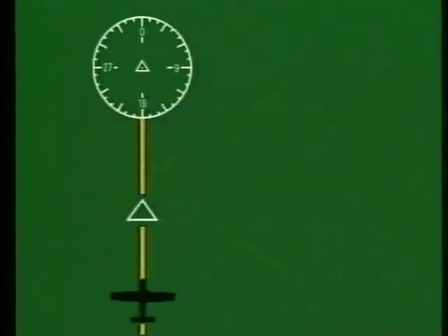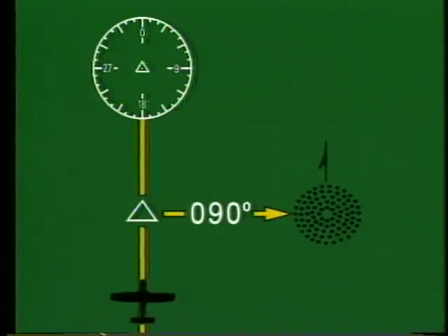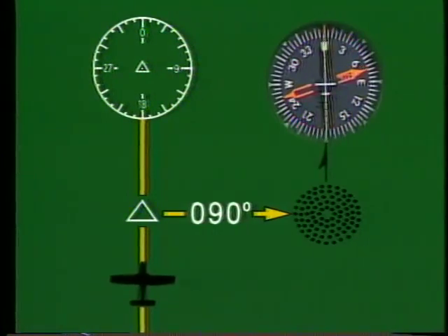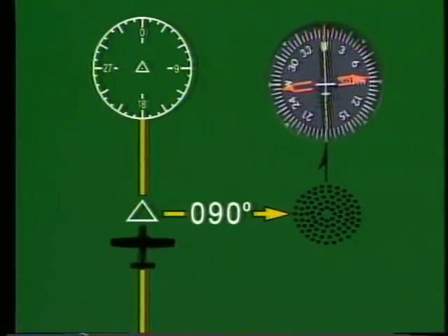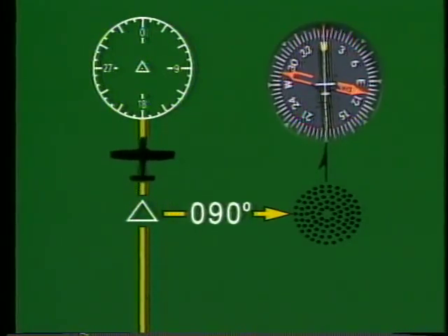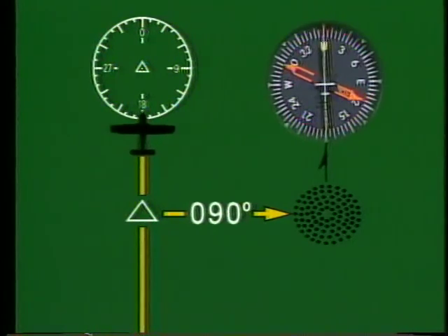To see how this instrument works, assume you're flying north along an airway on the 180-degree radial of a VOR. An intersection ahead of you on the airway is identified by the 090-degree bearing to an NDB. With an RMI, you can navigate along the airway with one needle while continuously monitoring the ADF pointer. When it points to 090, you are at the intersection. As you continue northward, the bearing pointers provide a perpetual display of your position relative to the two stations.